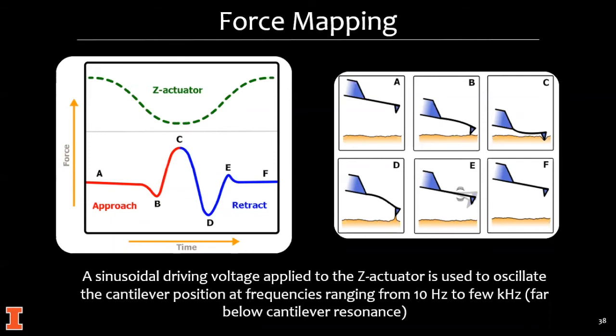So compared to tapping mode in fluid, tapping mode is so sensitive to the liquid environment and the changes in temperature, and so it makes it unstable. It's a dynamic resonating system in fluid. It's challenging. And also contact mode has these shear forces. So this mode eliminates both of those problems, and so it can get very precise imaging in fluid with low force control. So it's great. How it works is when you apply the sinusoidal driving voltage, you'll go through a cycle of this force curve.